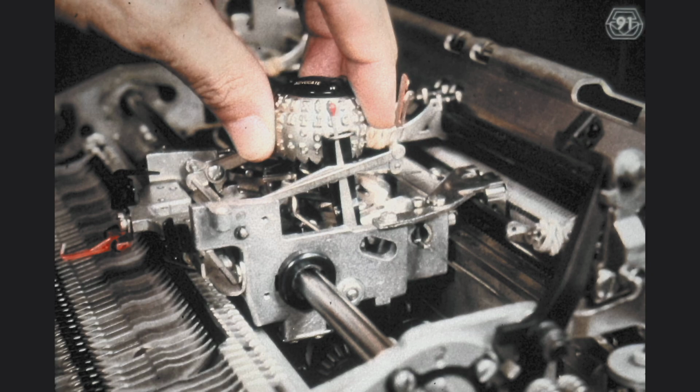We make sure it has been properly threaded or laid out around the pulleys, and then we can release the spring tension again. The purpose of releasing the rotate spring tension at this point is to make sure the rotate tape is kept taut while we work with the tilt tape. As you perform this step, make very sure that you release the rotate spring tension slowly, so that if the tape were to come off any of the pulleys without your noticing, you could still catch it and reposition it before you develop a kink in the tape.